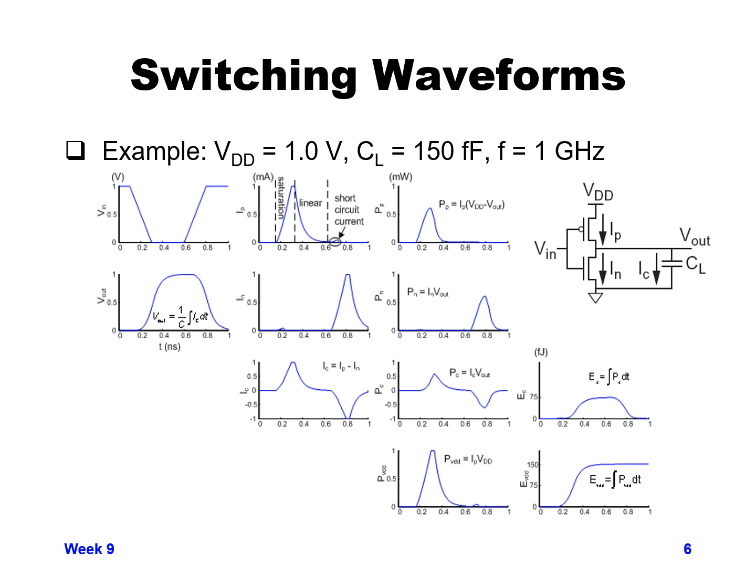And you can see right when the NMOS is first turning on, there's a little bit of a blip of short circuit current for the PMOS, because both the NMOS and PMOS are turned on at the same time, when your voltage is about halfway in between VDD and ground. And you'll see on the NMOS curve there's a little bit of a blip in the middle of the saturation region of the PMOS switching as well. Both of them are pretty small, so you don't see it very much, but that is a noticeable and measurable amount of current that you should account for.